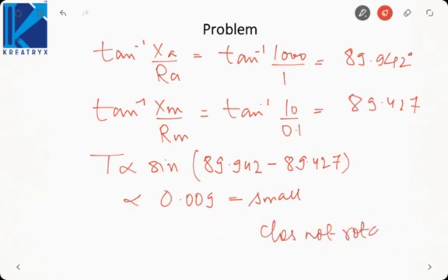Okay, because the torque is coming very small, the currents are almost in the same phase, and we need a larger phase shift to produce a significant amount of torque to rotate the motor. This torque may not be able to overcome the inertia required to rotate the motor. It may not be able to overcome the frictional or the damping forces inside the machine.